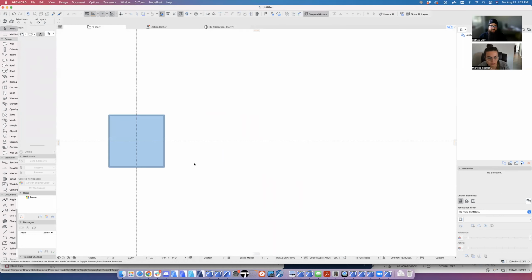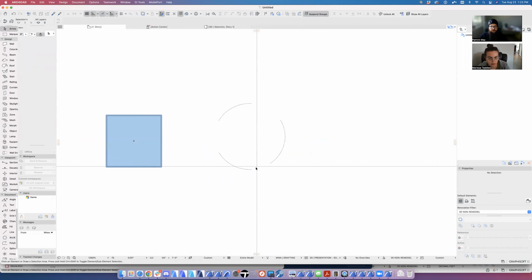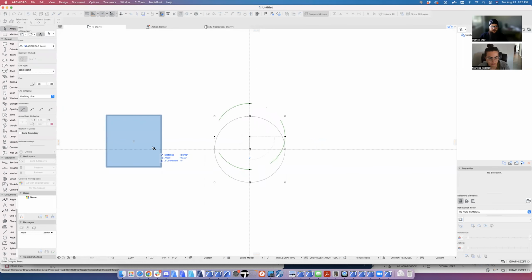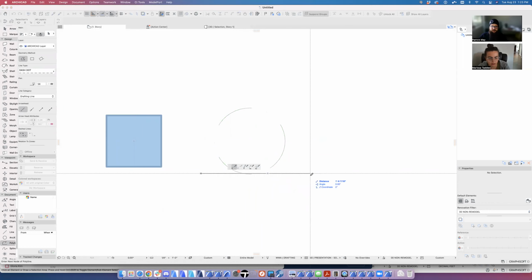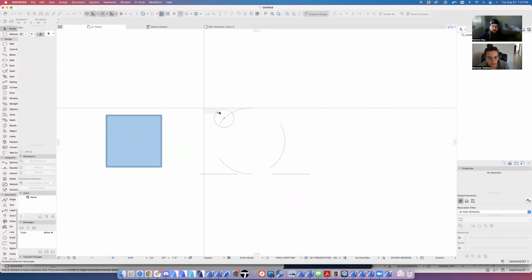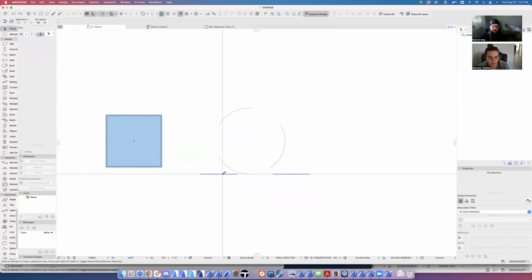And then on my floor plan, I'm going to say that my wall sconce fixture symbol, I'm going to draft this with arcs, lines, circles, whatever. From this point, I want this to associate to the center of this. And I can use whatever I need to, lines, arcs, fills, text even can work in here. But if this is my light fixture sconce symbol, oops, grabbing the wrong one.